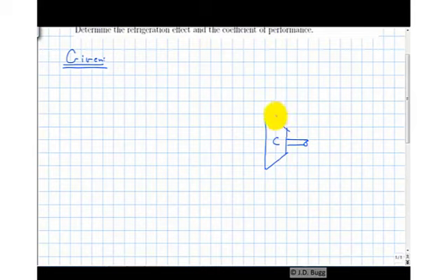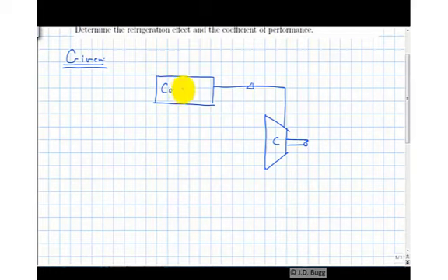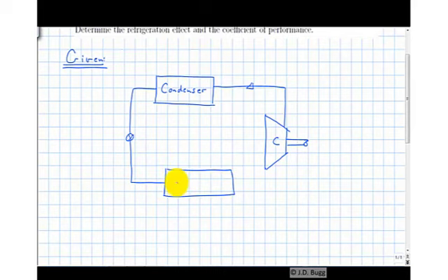The discharge of the compressor goes into a condenser. So we go out of the compressor, up into the condenser. We'll show the direction the refrigerant is flowing here. So this is our condenser. Then out of the condenser, we go into a throttling valve. And then out of the throttling valve, into the evaporator. And then out of the evaporator back into the compressor. So just show the direction of the refrigerant flow right there.